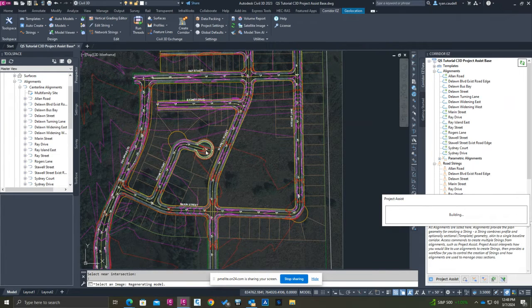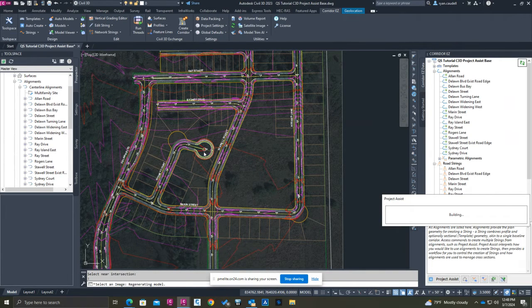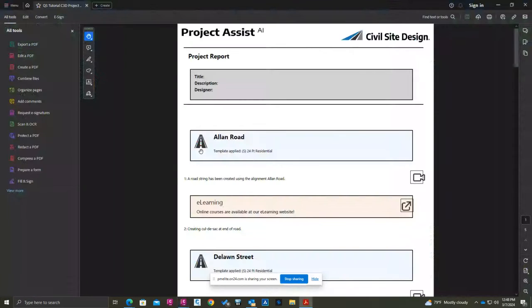You can see this cul-de-sac getting formed. I mean, think about how that would be done in Civil 3D. You got to spend time to go ahead and make an alignment around it. And then when you're trying to build a corridor, that's a new baseline, a new region. You got to run a template on it. It's a lot of little extra effort. And in Corridor EZ, it just seemed like it was just a tick box to get the same thing.